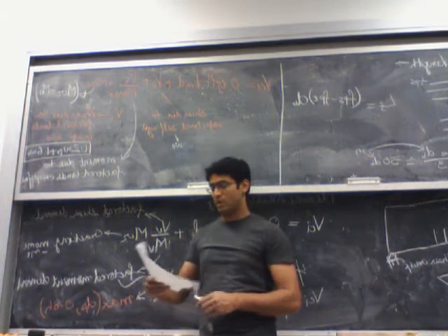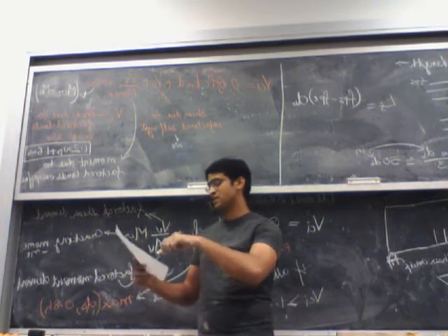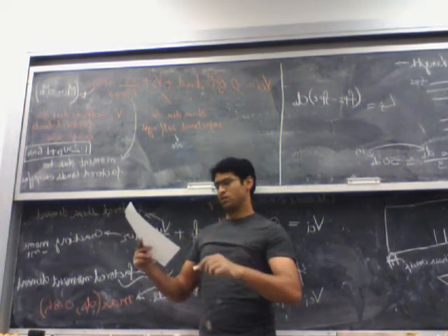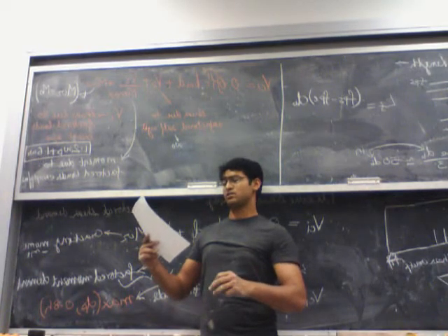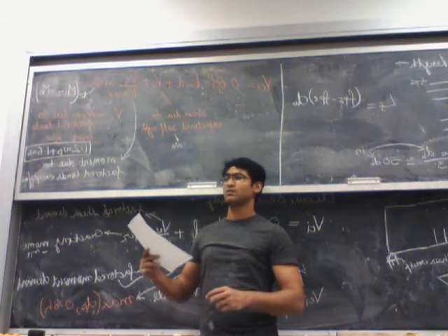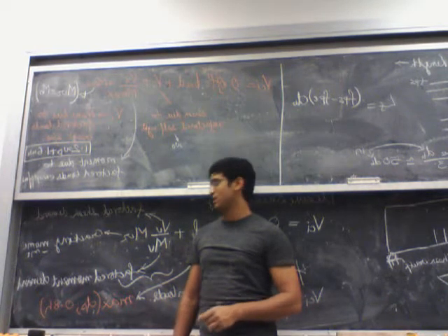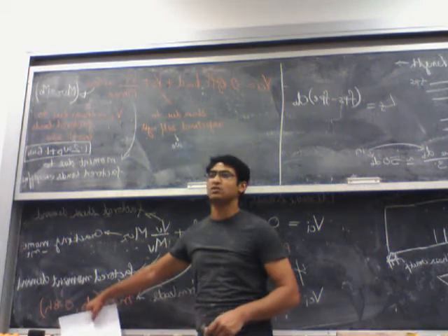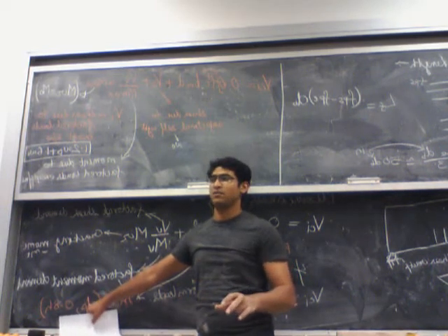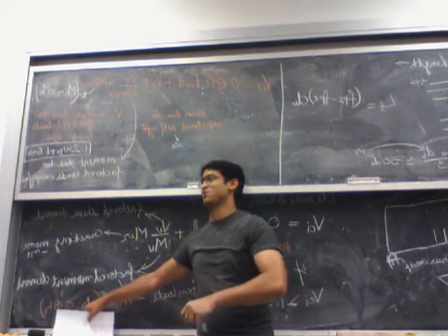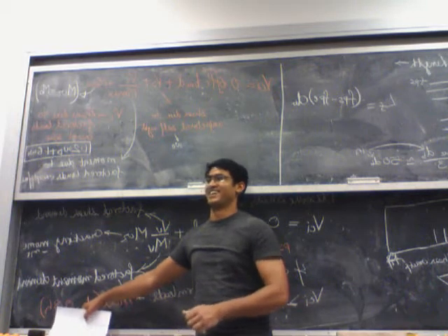But in my notes, I have it where he says, okay, it's, no, it's actually to the centroid of all the steel. Confusing, because there's dp mixed up. Yeah. So in this case, this dp is actually to the centroid of all the steel. Okay, so don't make that mistake. I'll take points off.